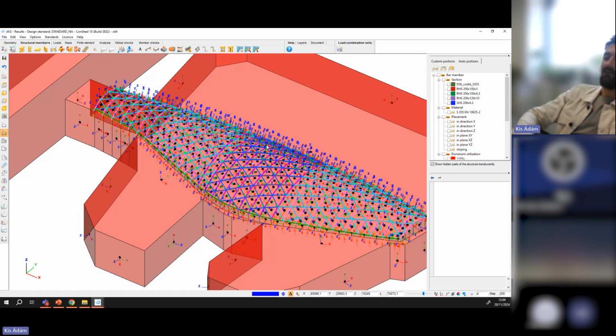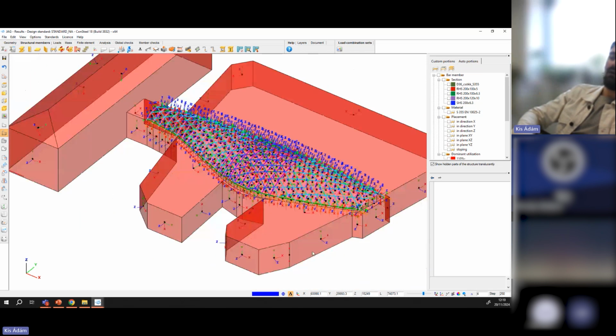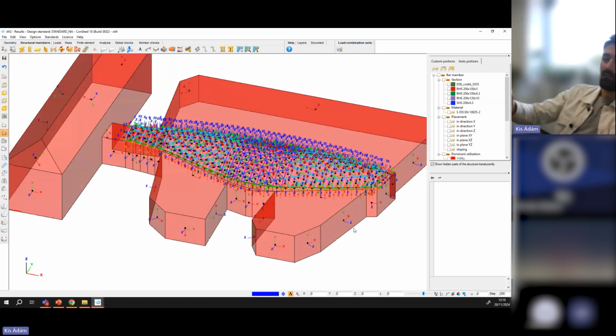But if we have a negative value on a wall, it is not straightforward in which direction the suction is applied. Therefore, when you are running simulations, you always have to take care that all the local coordinate systems point outwards from the structure.